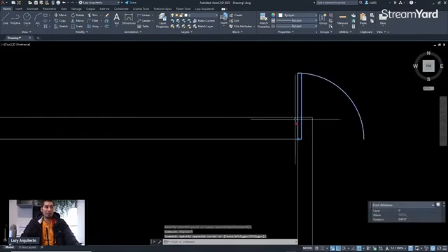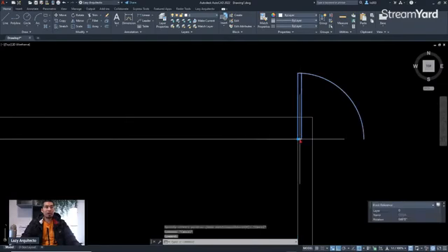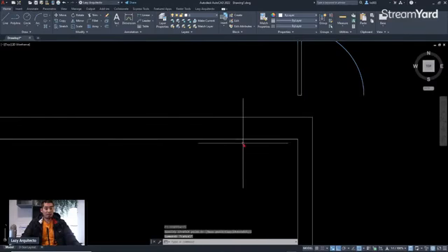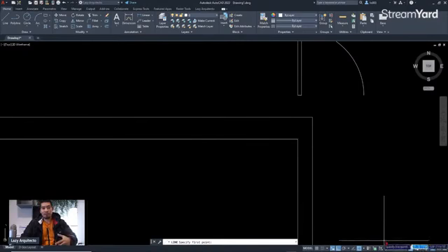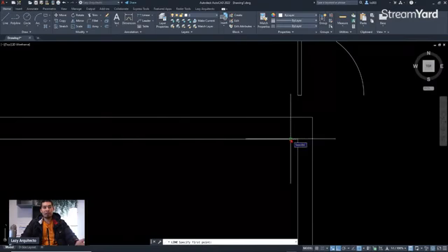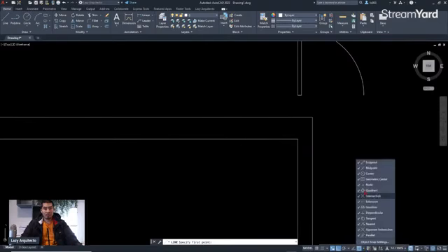At this point, what I'm gonna do is create an opening for my door, right? An opening over here. So I'm gonna draw a line, and I'm gonna turn off a precision setting for the first time because I don't need it, and it's giving me problems over here, which is the nearest. I don't need the nearest, so I'm gonna turn it off over here, nearest right here.